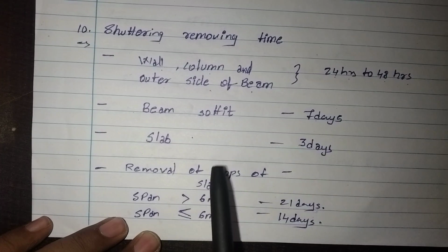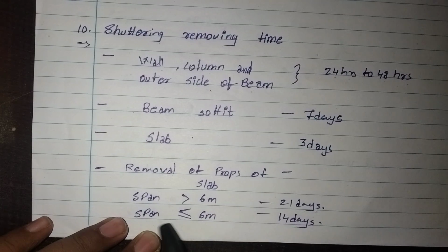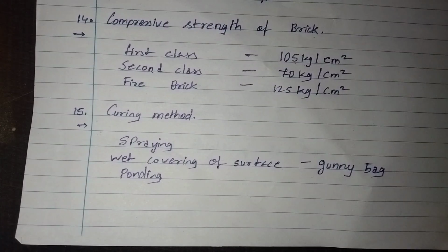But in terms of slab, if the span is greater than 6 meters, then 21 days, and if the span is less than or equal to 6 meters, then 14 days. Okay,